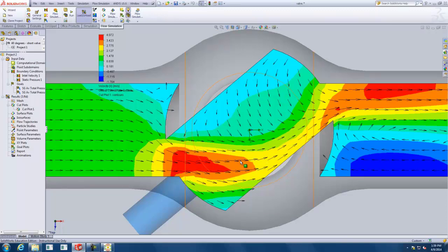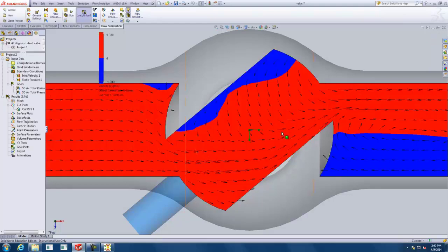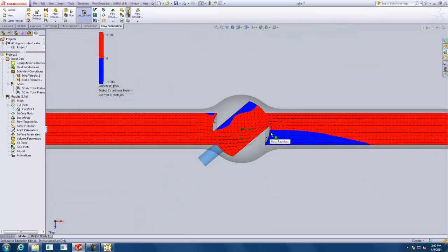Another thing we can do to really look at where the flow is going toward the inlet and where the flow is going toward the outlet: if we double click on our palette bar, it'll bring up our little dialog here. And we'll change the slider here. Instead of being 10, drop it down to 3. So we basically have two colors, blue and red. And then we'll do the maximum here as 1 meter per second and the minimum at -1 meter per second. And go ahead and click OK. And now we can see clearly the X component of the flow is going in the positive X direction when it's red and the negative X direction when it's blue. All right, so again, just a nice visualization possibility there.